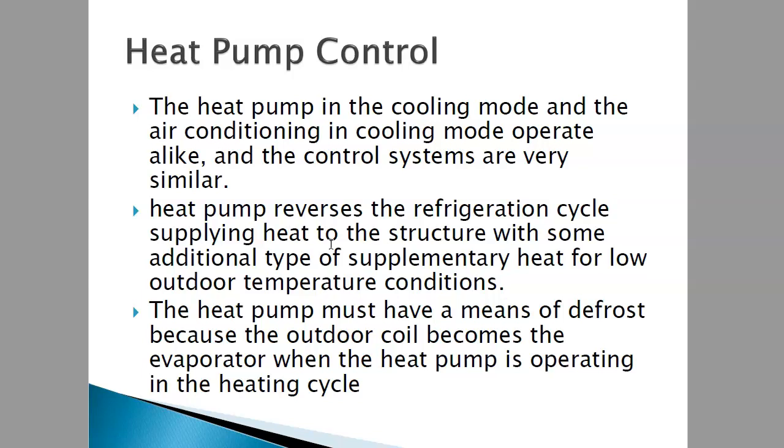So for the heat pump to operate in good condition, it has to have supplementary equipment that can defrost whatever ice is made inside the outdoor system. That's for heating.